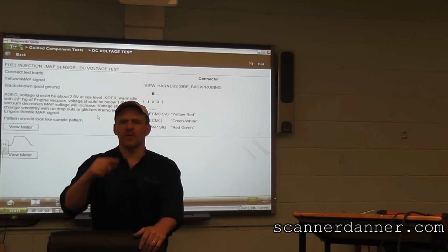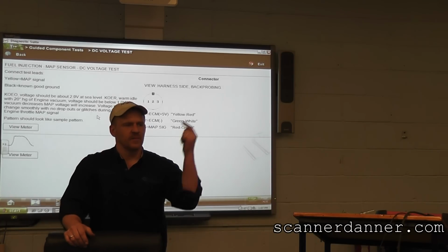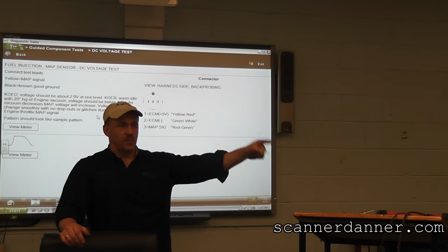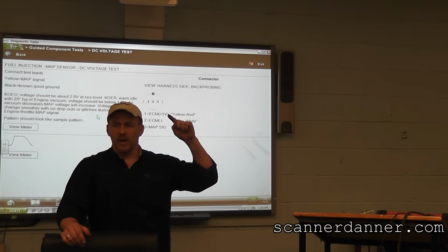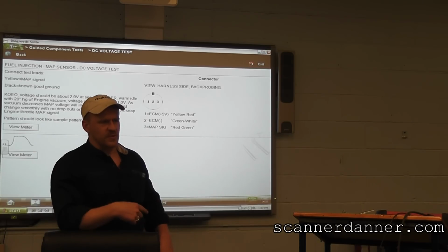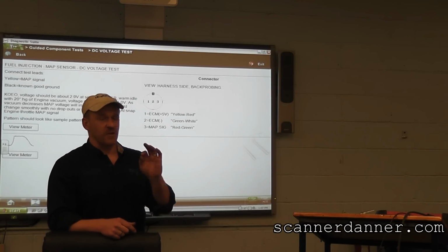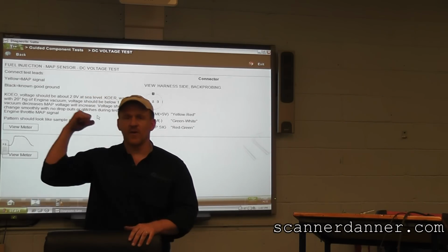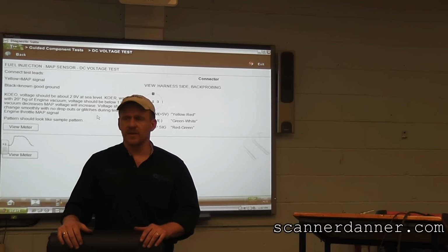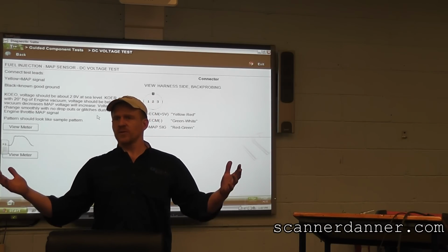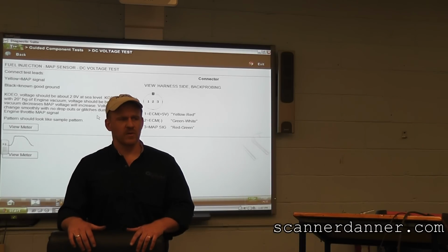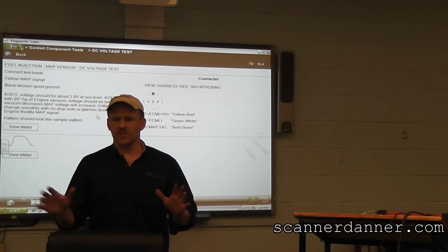All right, so we go to shop. What do I want from you guys? Pull the car in, test drive, verify complaint, pull your fault code, look at your code tips on the troubleshooter, find symptom tips on the troubleshooter. If you have a specific component, you think you can handle it, follow your guided component test meter and do some checks under the hood. Okay, and I'll help you, of course. That's what I'm here for. But I want you to be able to do this too on your own. Cool? Yep. Any questions on this car?